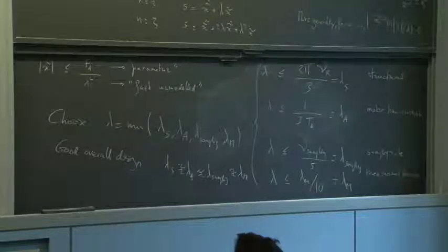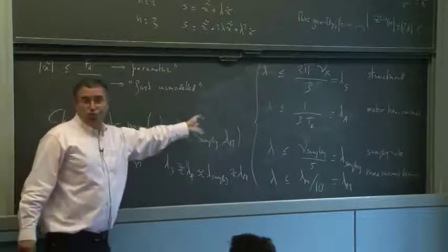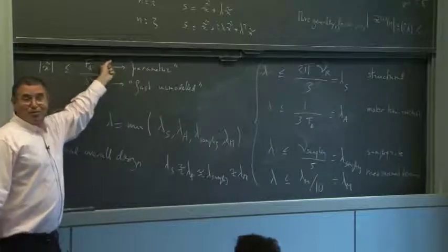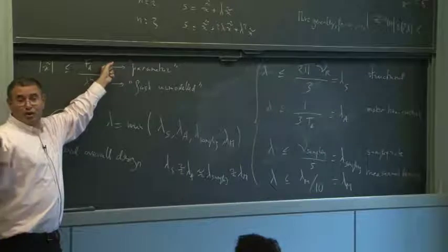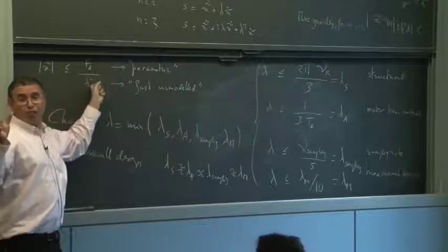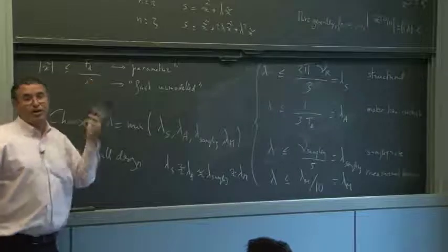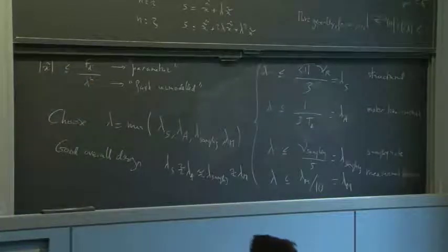So if sampling is your real limit and you can't change the computer, by all means simplify the model. Because here this is varying linearly with errors in the model, and this is varying to the power n. So basically sampling should never be your active limit, because you can always simplify the model so that it goes to the next one.